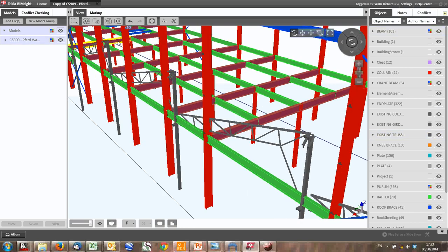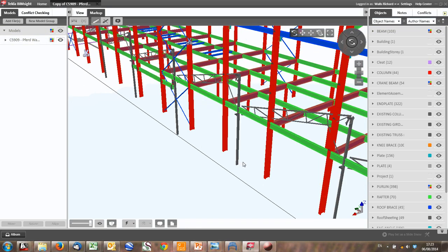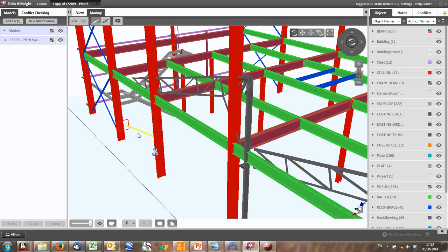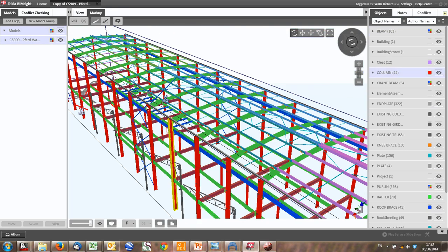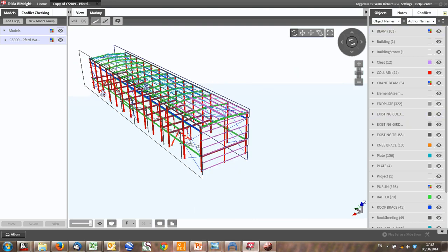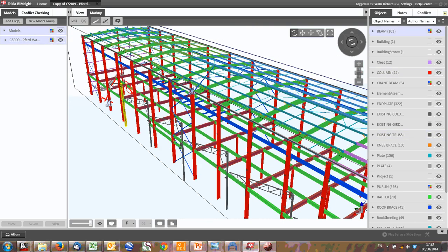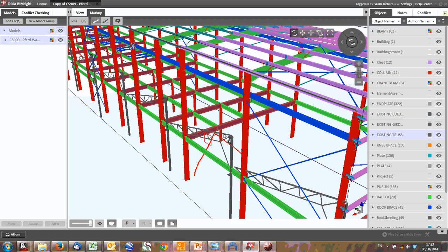So, if we now add a bit of bracing on this side, and we'll add some here, and bracing there, K-brace, that will allow people to drive through, or we could add in a cross brace. And we add in a K-brace here. K-brace. There we go. You can actually then span the load from there to there, and then the lateral load can be taken by this floor, and then taken all the way down to the end bay, and you can just design that brace to carry the load.